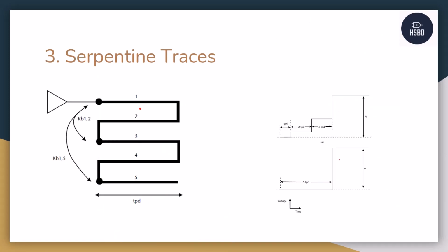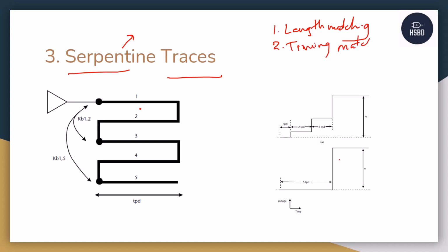Now the next part is usage of serpentine traces. First of all, let me explain what serpentine traces are and why we use them. There are two factors that are involved. One is length matching, and second is timing matching, or you can call it delay matching.